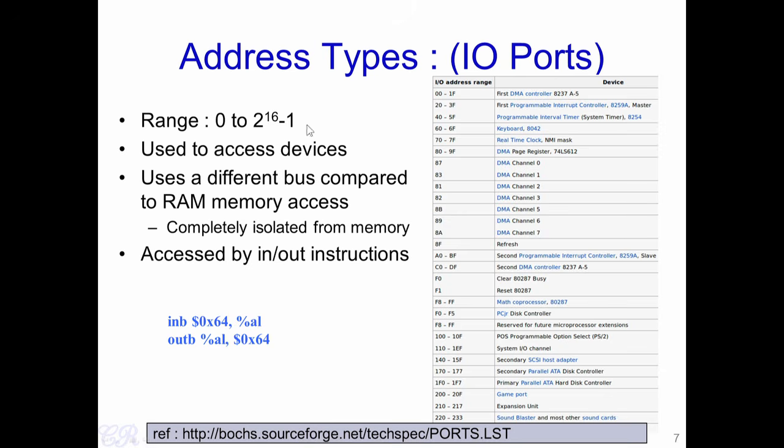So, this is roughly around 64 kilobytes, and the IBM PC standard would define what the use of certain addresses are. The IBM PC standard is a standard which was followed to develop systems, especially the desktop systems and certain servers, and this standard mentioned what devices should be present in what I/O addresses. For instance, it mentioned that the keyboard should be present between 60 to 6F, so the I/O address 60 to 6F.